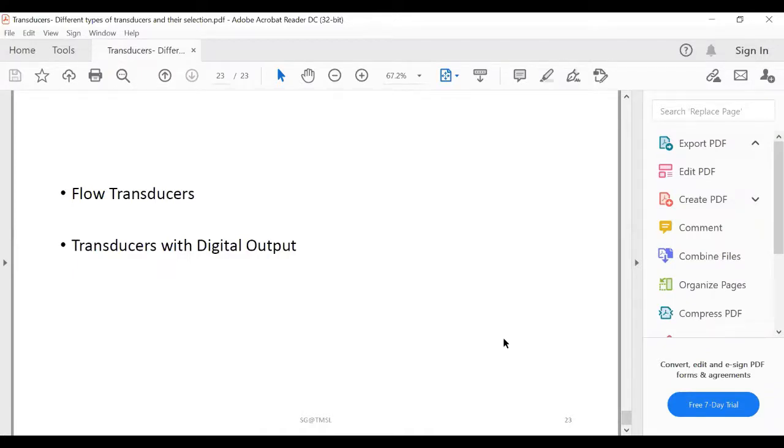Encoding discs or rulers with a digital pattern, photographically etched on glass plates, can be used. A light source and an array of photo detectors, usually made up of photodiodes or phototransducers, are used to obtain a digital signal in parallel format that indicates the position of the encoding plate and thereby represents the displacement that can be measured.